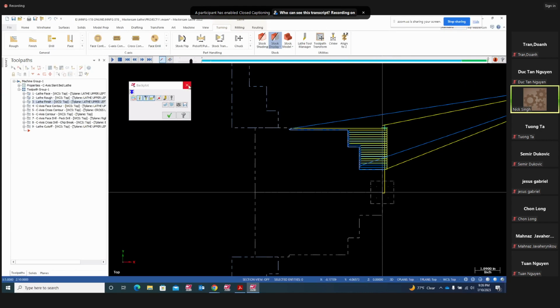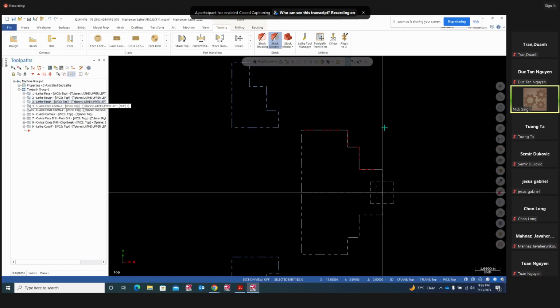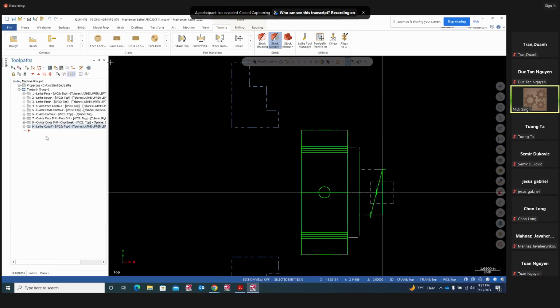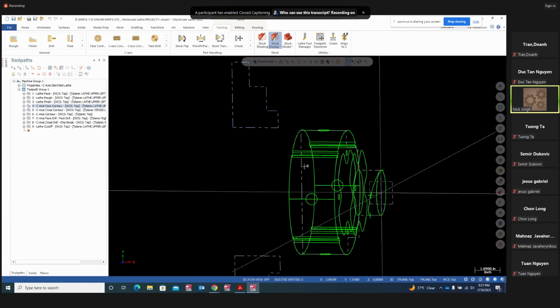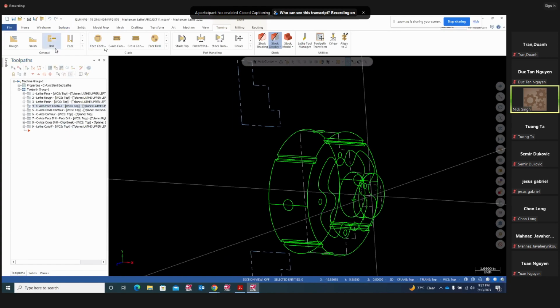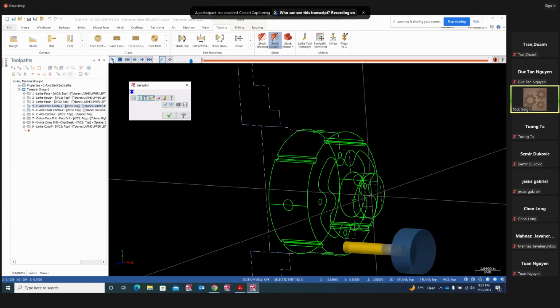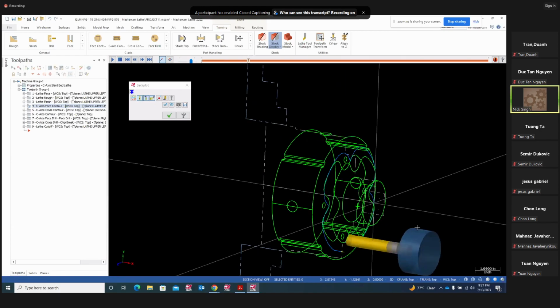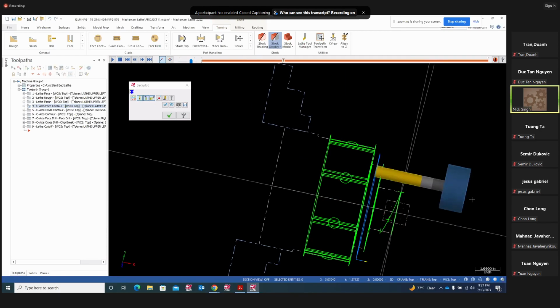And there we are. So then start your C-axis: face contour, cross contour, axis contour, face drill, cross drill, and cut off. So now I can go to level. I can turn that guy off and turn this on. And there comes my next toolpath, which is going to be lathe C-axis face contour. It's going to cut this guy. There you go. We are doing multiple passes over here, Z-step.